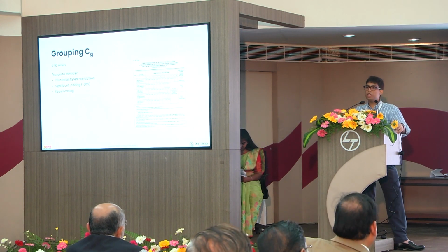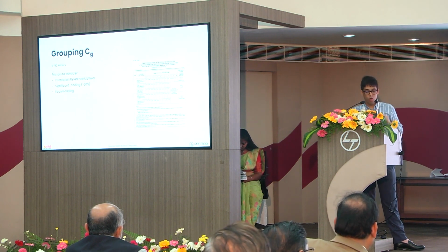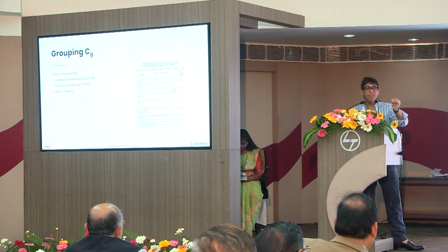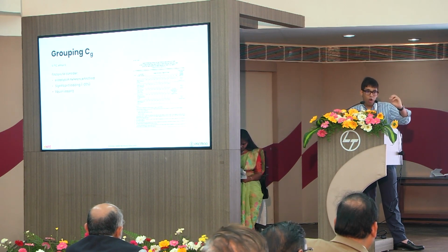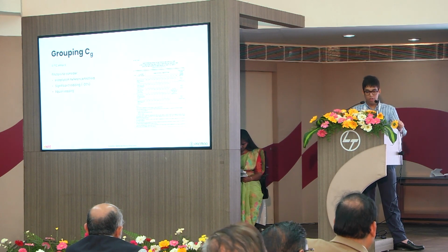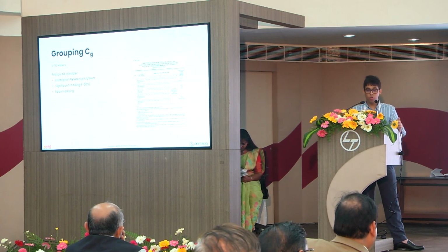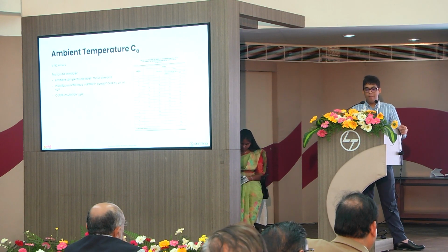But now you might say that a socket circuit will have barely any load, so we can say less than 30%. That is not true, because a socket circuit is open-ended. You can connect any device, any appliance. Only when you know that a circuit cannot go above a certain load under normal conditions, such as a lighting circuit with only lighting connected to it, can you then not consider grouping. Also, these factors are for equally loaded cables. For cables of different loadings, please refer to Annex S and IEC 60287. Now, ambient temperature.